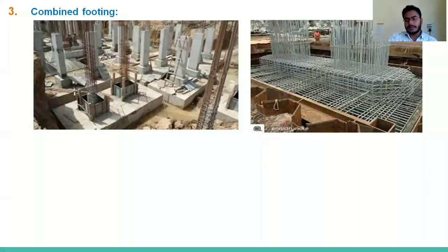We do these types of design when we are getting heavy loads on both the columns. You can see in the case of a bridge, there are heavy loads coming on the column, so in that case you will see this type of thing. This is one of the examples, so you can get the reinforcement detailing and some actual idea of what they are doing. For other purposes, when we design the combined footing, we design the reinforcements according to the loads, and there are various factors, so you can get a different shape or different reinforcement detailing also. So there is no issue, right?